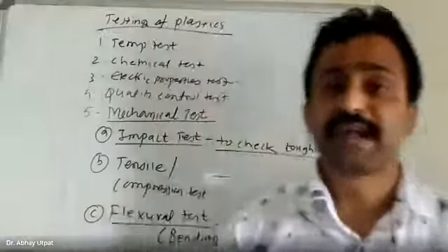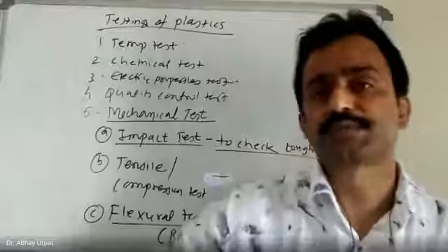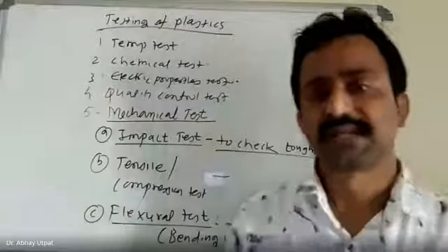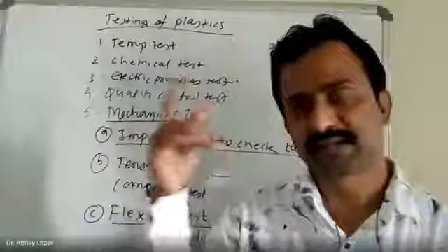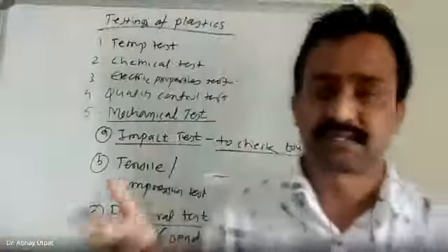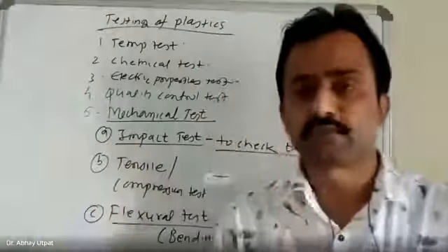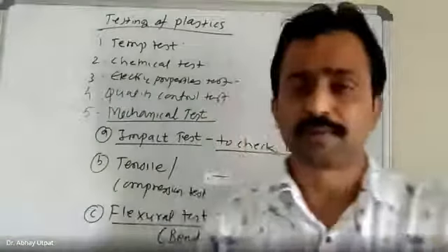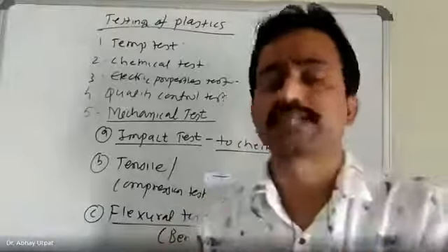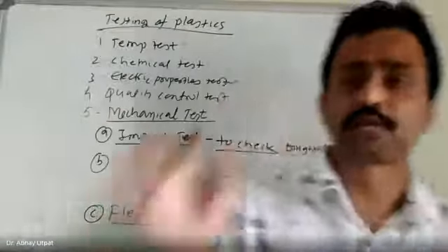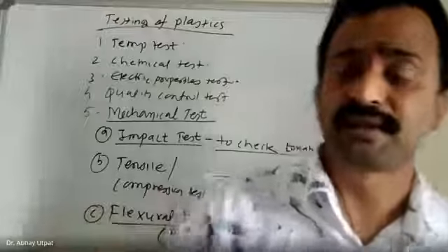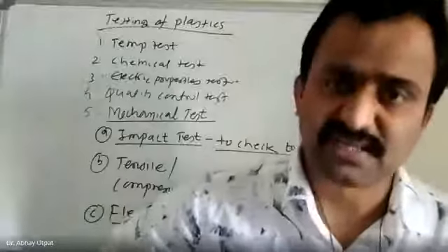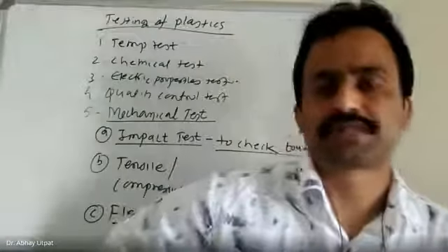Then we have seen additives in the plastic. Additives means the elements which are added in the plastic for improvement of the properties, starting from plasticizers, flame retarders, colorants, fillers, stabilizers, etc., which give extra strength to the plastic, depending upon the requirement. Colorants are added for a good aesthetic look. Stabilizers are added to maintain stability. Flame retarders are added for avoiding catching of the flame. Fillers are added just for saving the cost.